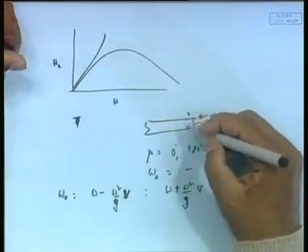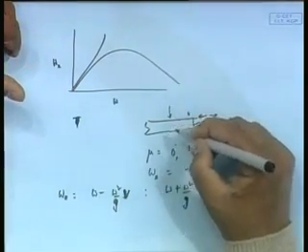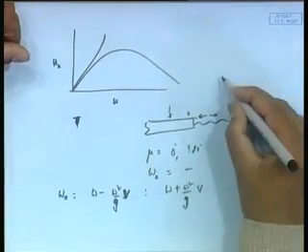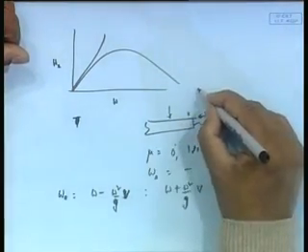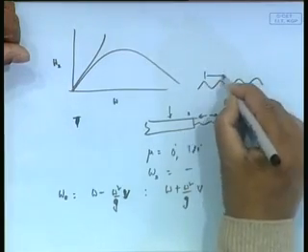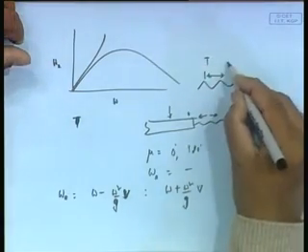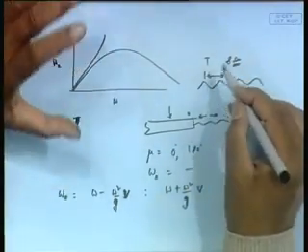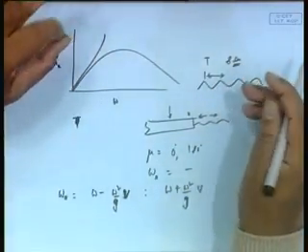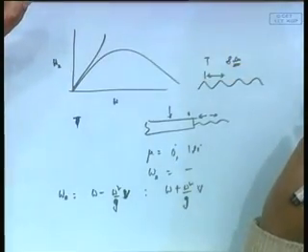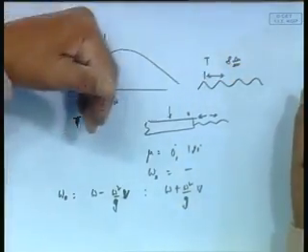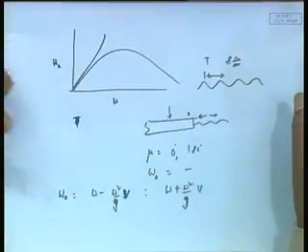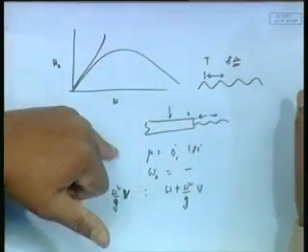That is what I am emphasizing. If you have an instrument here, you are measuring excitation. So what is happening, I end up finding that my body has an excitation of this period TE, say 8 seconds or whatever. Please understand that this 8 seconds might arise from multiple scenarios if it is a following wave, because I could have 2 omegas which could have given rise to 8 seconds. So unless I know that, I really cannot figure out the motions properly.